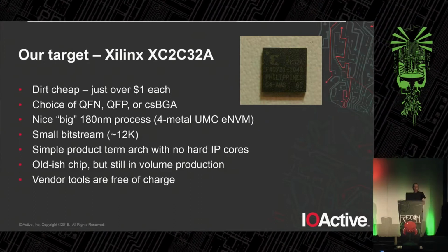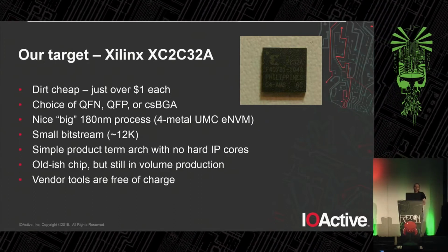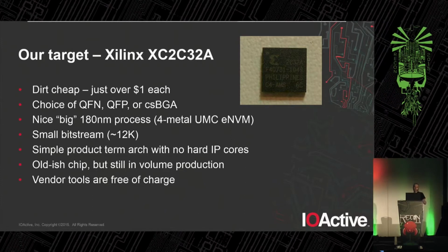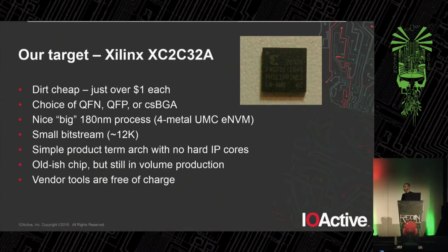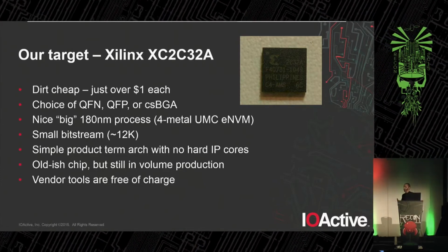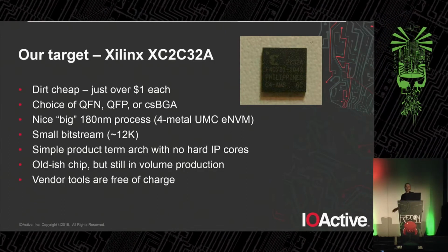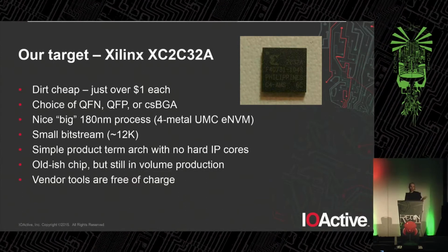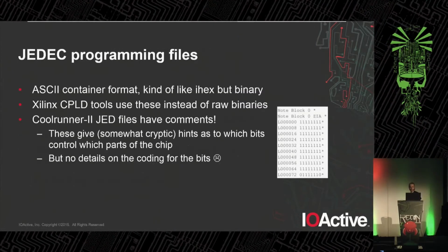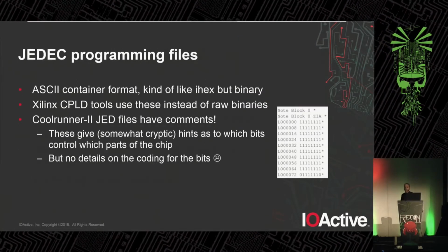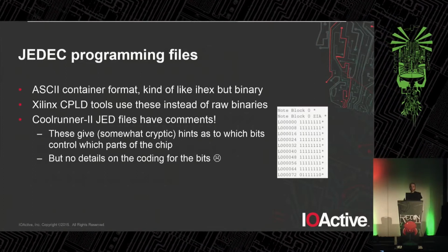The bit stream is also not that big. It's around 12K, so there's not really that much there to reverse. And it's also a fairly simple architecture. You're not going to find block RAMs and embedded ARM cores and all kinds of stuff like that. It's just pure programmable logic. And the vendor tools are free, which always helps. Hackers are cheap.